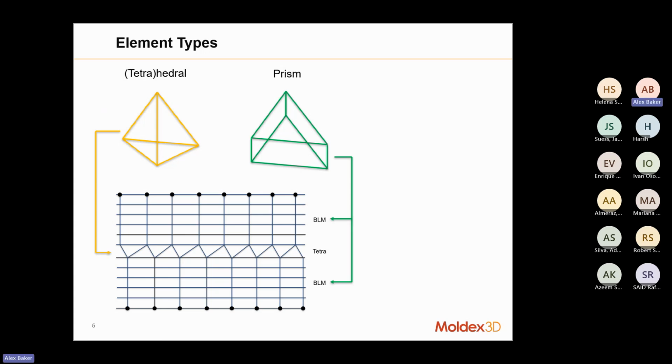But they do actually kind of fall flat in any sort of high deformation analysis. In molding analysis, it's fine because it's pretty low deformation. But once we start getting out of that linear elastic range, these prism elements end up being poor quality, whereas they are extremely high quality for flow analysis. So we use them in Moldex3D, but when you get over into your structural analysis, you'll want to use something more like a tetrahedral element that's a little bit more flexible.